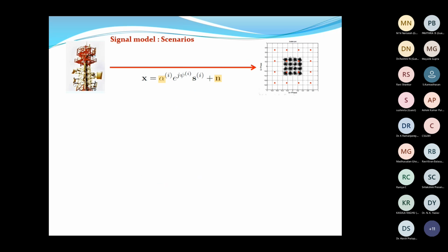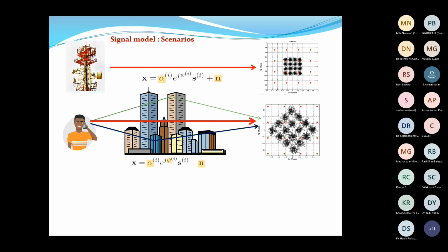So in the context of the various transmission scenarios, we have the simplest case of signal attenuation, when we don't have any reflections or any fast fading scenarios. So the received signal has only amplitude variation. Then we have the scenario of static multipath fading, where during the observation interval the parameters don't change. In this case, we have the amplitude variation, the phase offset, and the noise. These are the unknown and random factors to be considered.